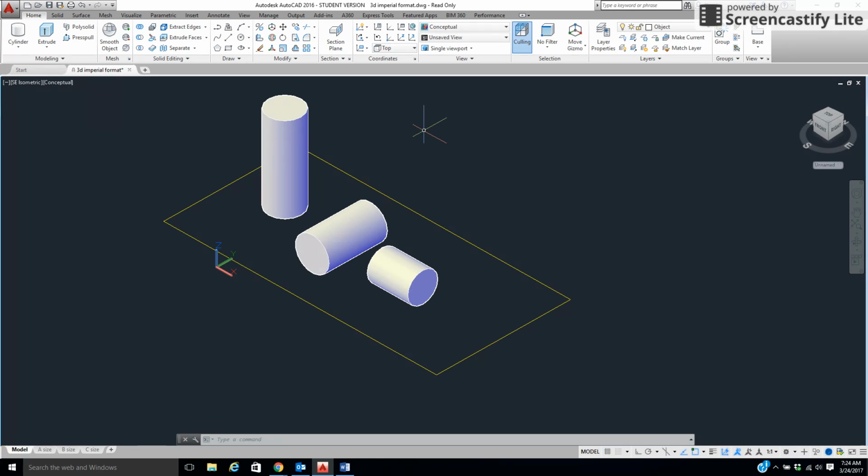Now, I do want to make you aware of one of our snaps that we have that really can cause us some problems. If you're an advanced student and you understand the UCSs and you understand how things are going, this may be helpful. But if you're trying to do things in specific ways, this will not help. See this one right here? It's called Dynamic UCS, and it's actually your F6. So you can toggle and make sure that's off.